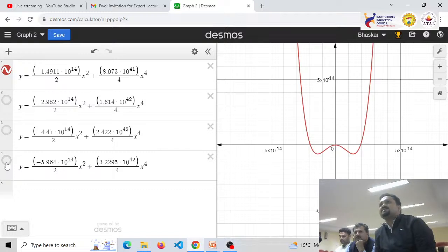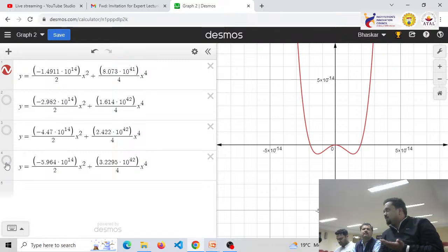Here in the case of ferroelectric capacitance, the energy stored in ferroelectrics is governed by the equation U equals alpha by 2 QF square plus beta by 4 QF to the power 4 plus gamma by 6 QF to the power 6. But here I have restricted myself to only two terms, alpha and beta. As I have already told you in my previous graph how I got the values of alpha and beta, those alpha beta values remain the same as what I obtained in my earlier explanation.